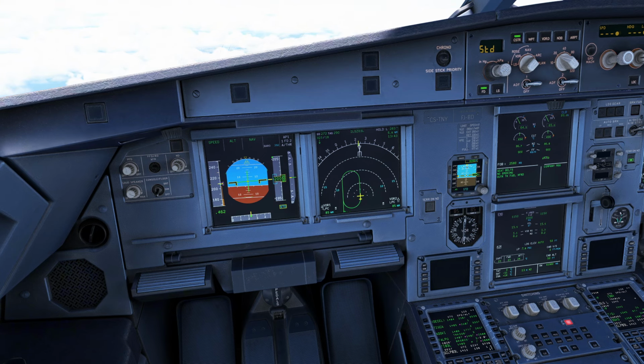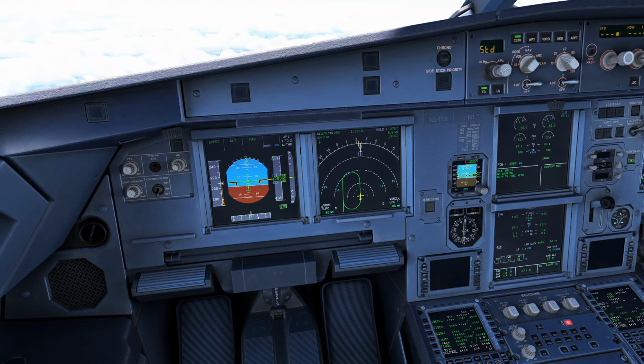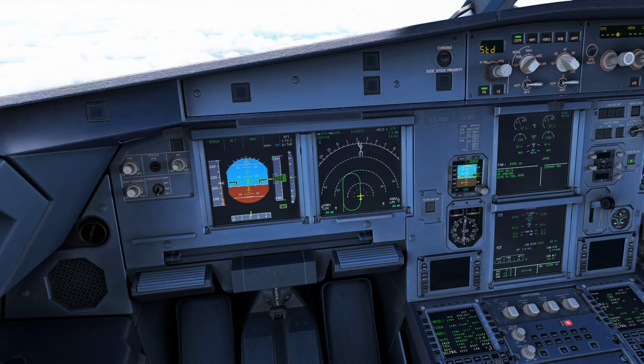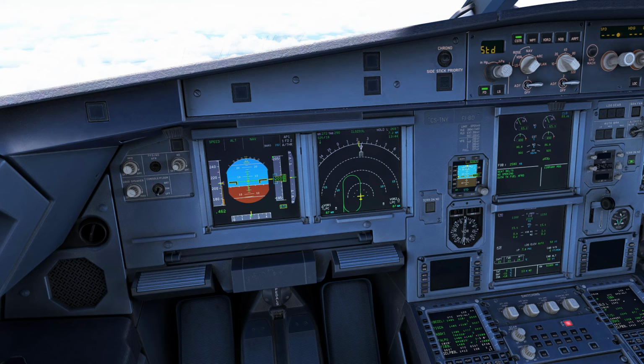But you have to make some considerations for the decelerated approach when you are going at higher speed. It requires precise timing and energy management, and higher pilot workload due to configuration changes during the final segment, as I told you already. It is not ideal for short final or time-critical situations, and must be stabilized by 1000 feet or 1500 feet AGL in IMC, or 500 feet AGL in VMC.